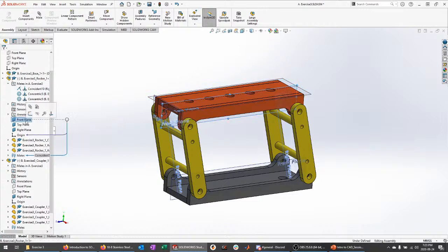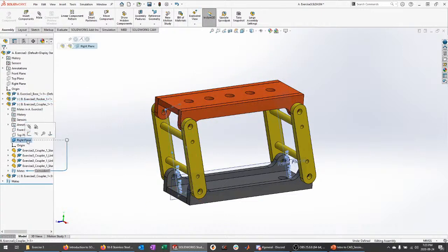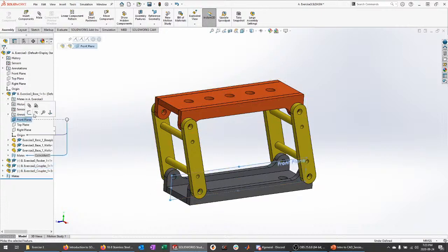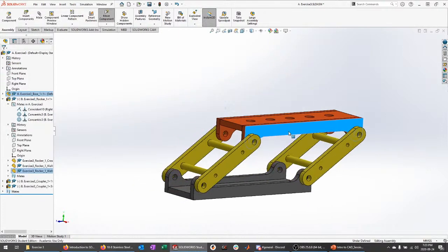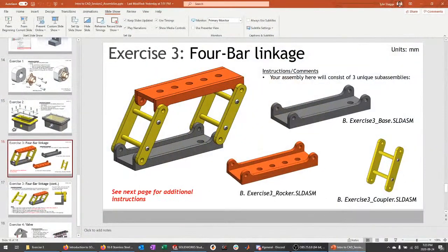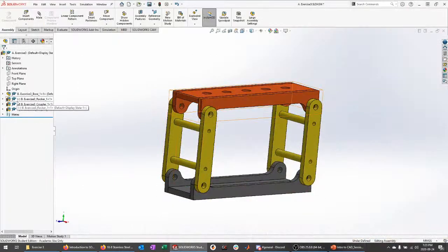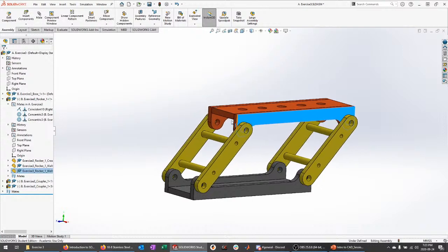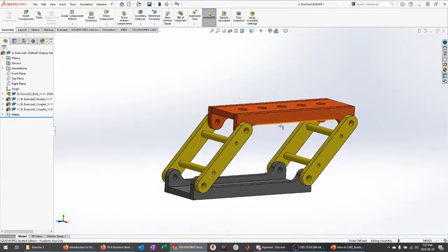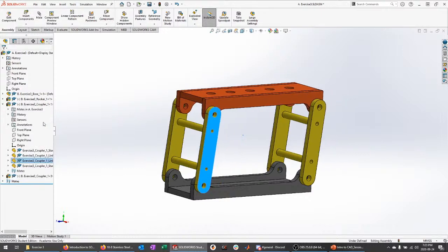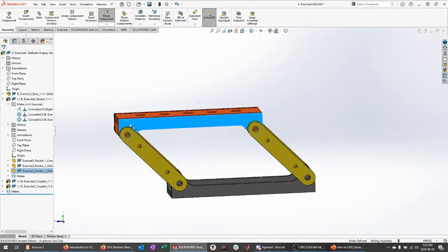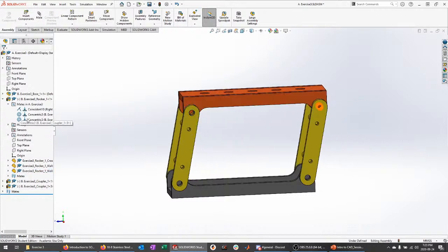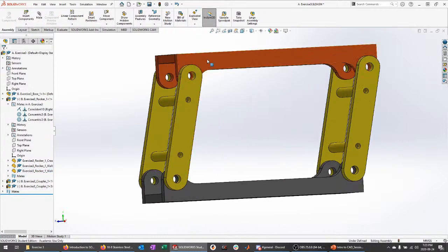All right, cool. I'm going to go ahead and hide some more of these planes just to declutter things. But yeah. So we now have, this is basically what we wanted here. You'll notice that there are still these characters, the parentheses, dash, close parentheses. So this is not fully constrained, but we don't want it to be fully constrained. We want it to be constrained in exactly the way we want it, and that's what we've done by applying the constraints in the way we have. Now, if you do have situations or systems like this that have a degree of freedom, but let me rephrase that.